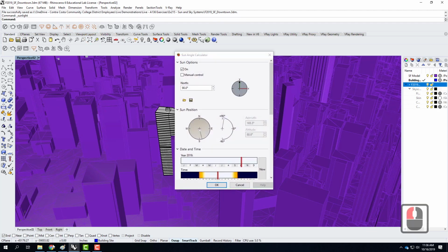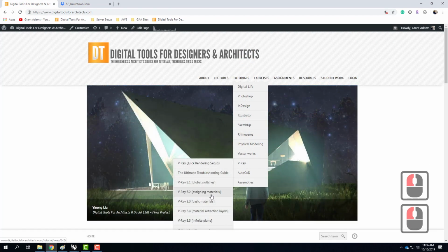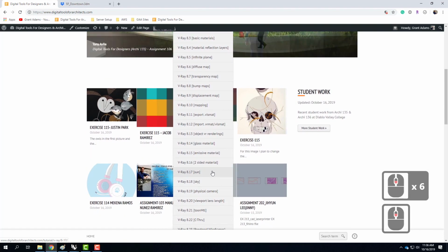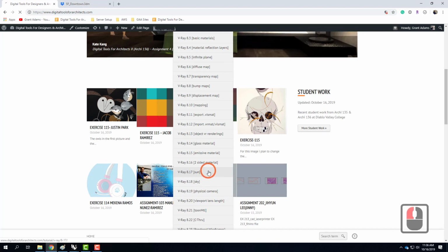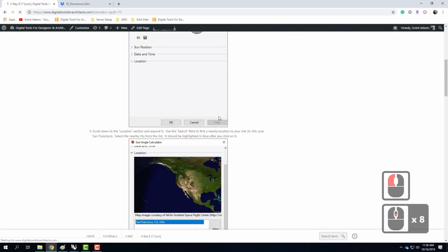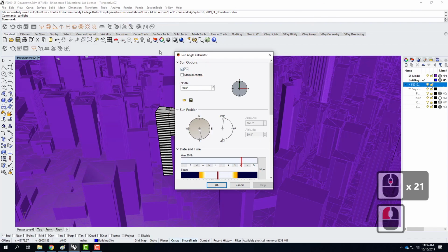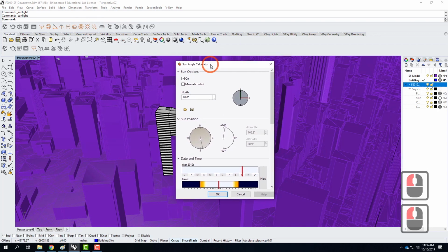I should also point out that I have updated the tutorials on the course website. So if you go to tutorials and you go to VRay and you come down here, we're going to be working today with 8.17 for sun, 8.18 for sky, and 8.19 for the physical camera. So all of those are worked out. So everything that I'm about to do is written out right here, so you can go in and double check. So I've gone ahead and I've started the sun creation toolbox. So here we go. Right there, I click on the sun icon, and then I get the sun angle calculator dialog box.